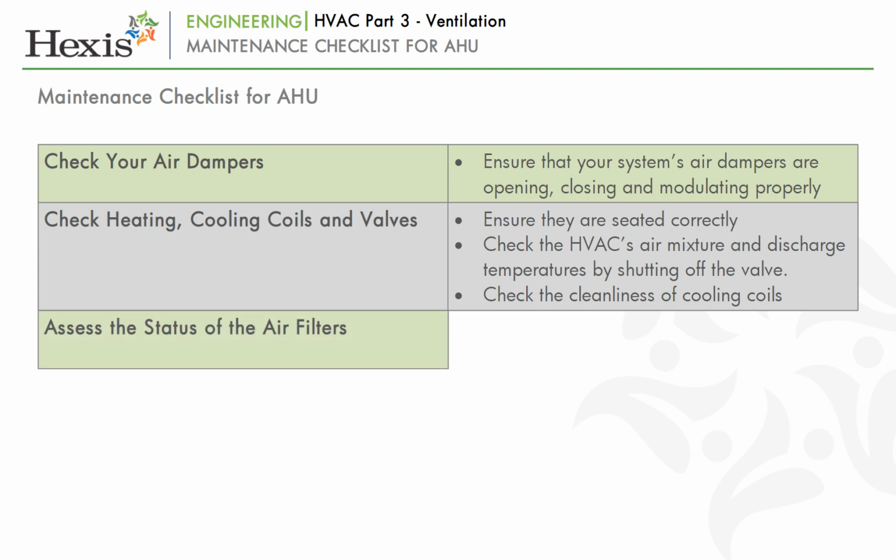Assess the status of the air filters. Static pressure sensors are used to determine how dirty the air filters are. Unclean air filters waste your facility's energy. The fan system needs to work that much harder to account for airflow obstructions. The air filters should be changed as soon as possible if they aren't slightly opaque.